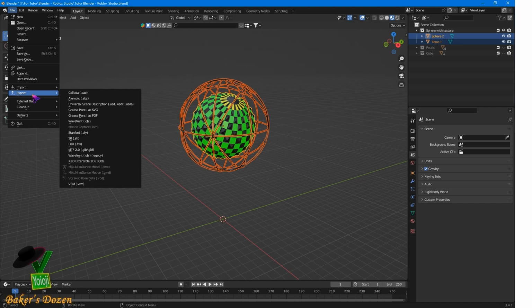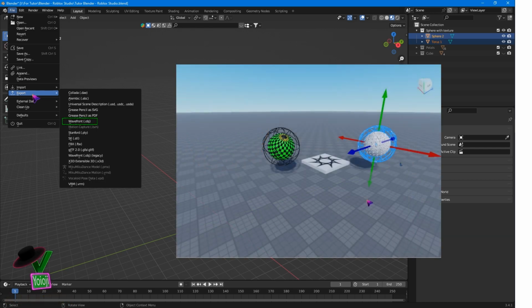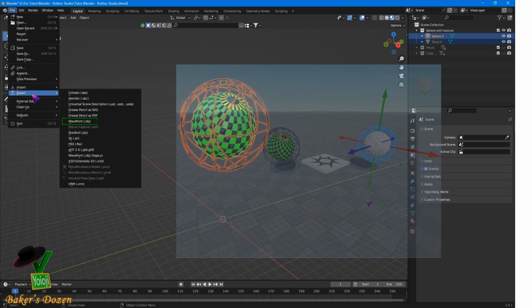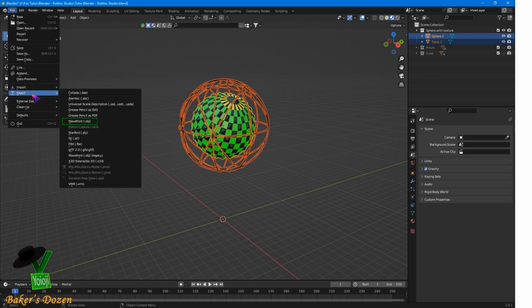Here we have only two options that Roblox Studio works with. They are OBJ and FBX format. There are several differences between these formats. The cons of the OBJ format: it does not automatically add a texture, that is, you have to add it manually. Also, if your model consists of several parts, then when importing into Roblox Studio, all parts will be combined into one. Of the good, an adequate size when importing.